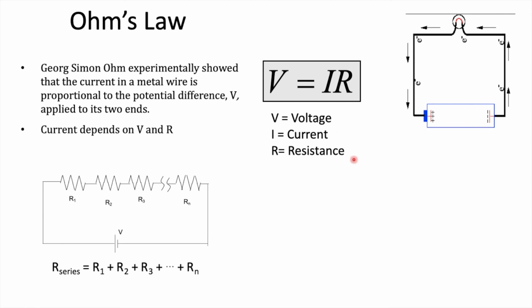And we can put these resistors here. This one here, we are using as one resistor. Also, it's important to note that for most of our lab examples, or even in lecture problems, when we add a high resistance resistor here, we ignore the resistance of the wire itself. Compared to these resistors, the resistance of the copper wire is very low, negligible, so we ignore that.